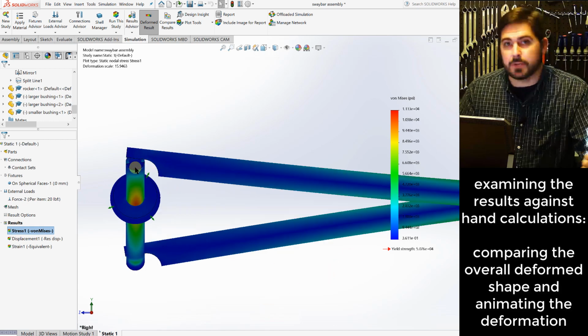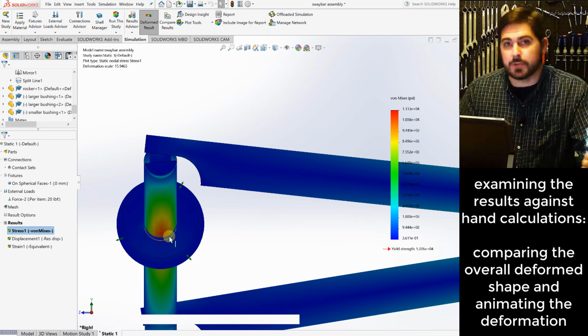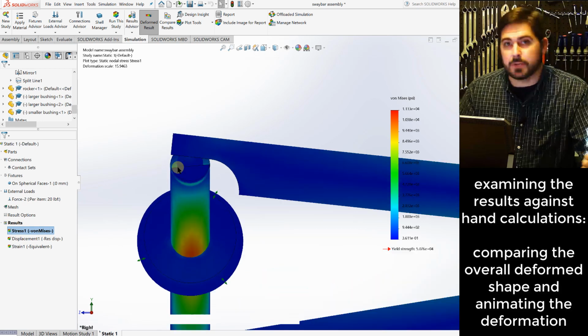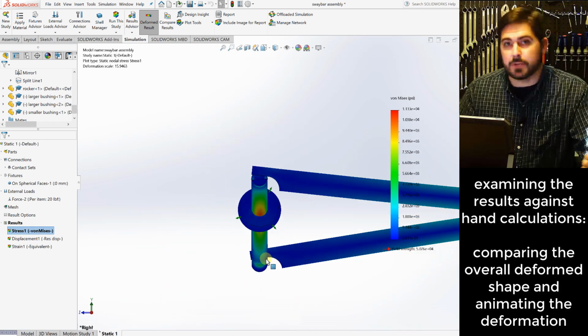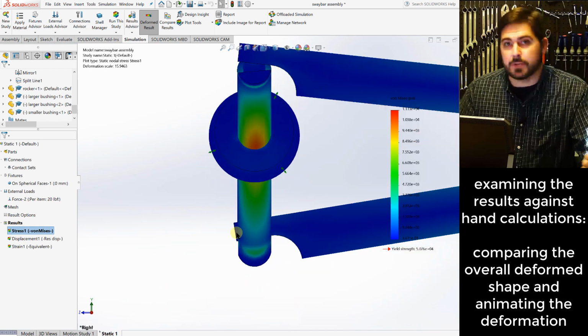Here's another interesting thing I was going to show you. The angle of this end of this piece basically still corresponds with the angle down here. That's the friction factor that I applied on the ball on the opposite end, but not on this ball. That friction factor is stabilizing the rotation of that member, and because it has that friction factor and no other friction anywhere else, it basically is just going to move angularly down its axis so that it matches whatever this member is that comes in right here.